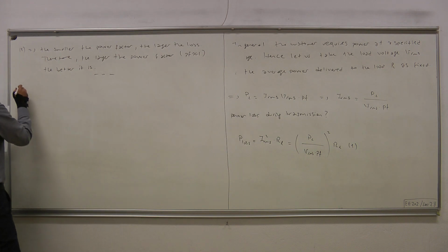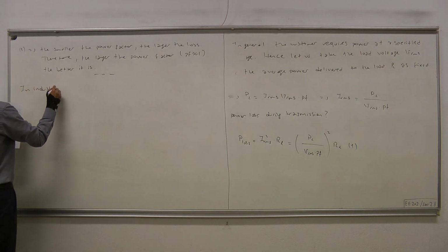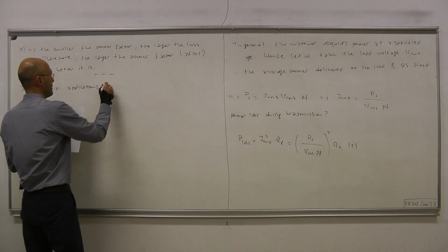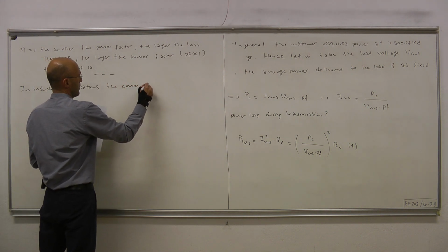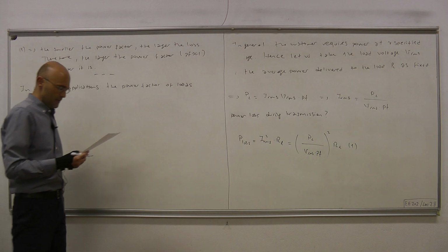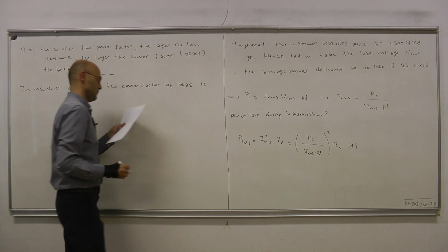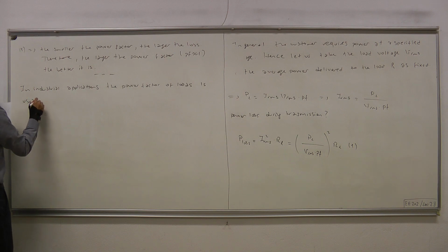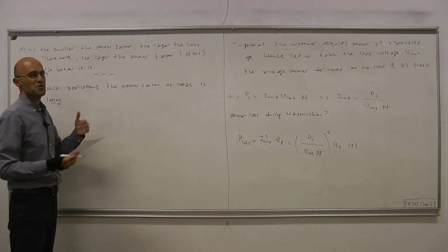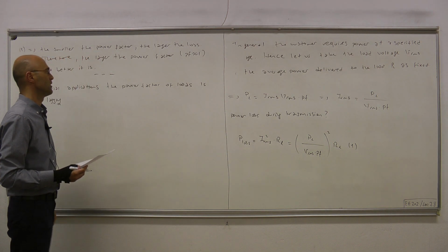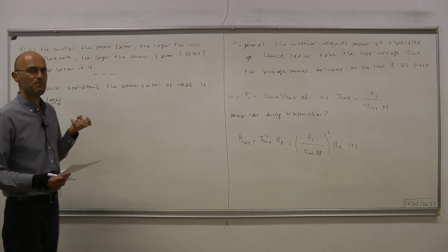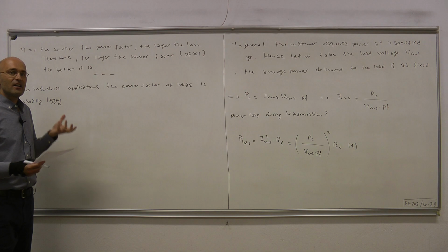Okay. Now, in industrial applications, the power factor of loads is usually lagging, and the reason for that is in industrial applications there are many electric motors that are doing some work, and electrical motors have windings, therefore they are in a sense inductive equipment.